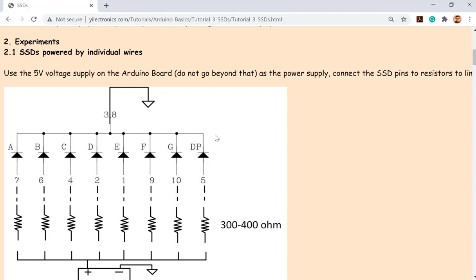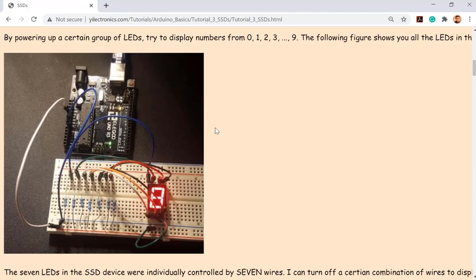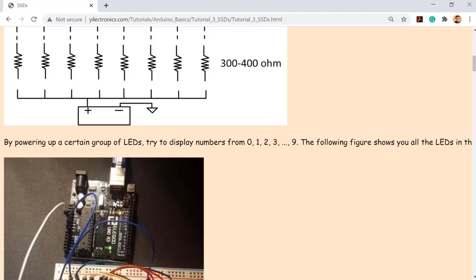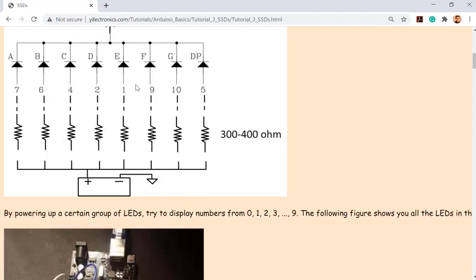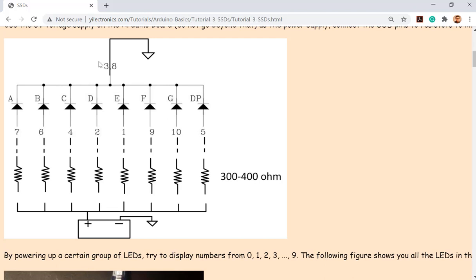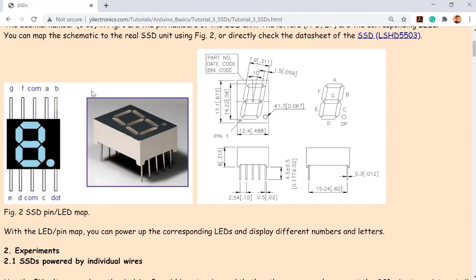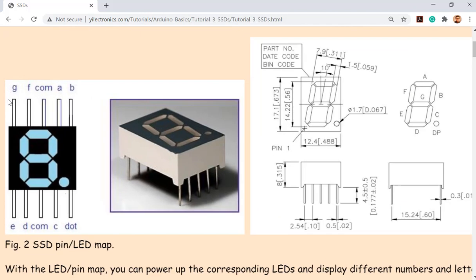That's okay. So see what I did in the past. I have 8 220 resistors being connected to every LED. But you don't have to do that. You can just connect one to here. So if you look at the pin out for this device in your box, COM is a common cathode.